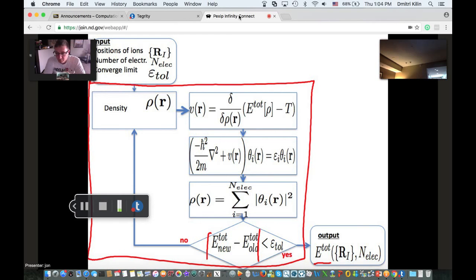Okay. So if you're ever going to look into the OUTCAR file, you're going to see that there's a number of iterations and then printouts of total energy at some given time step. And so different steps require a different number of calculation steps in between them, given how far off of the convergence criteria they are, or how far off the geometry might be.